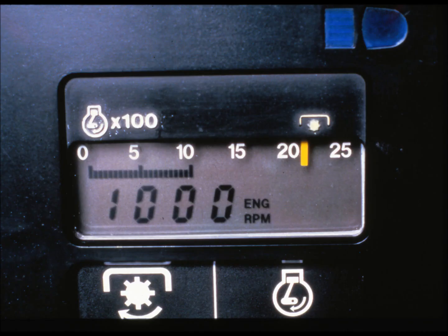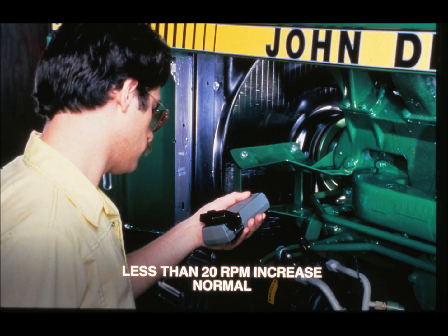With the rock shaft up and all other control valves at neutral, run the engine at 1000 RPM with the pump in stroke. Record engine speed before and after destroking the main hydraulic pump. If the tractor you are diagnosing does not have a digital tachometer, use a photo tachometer. Precise RPM readings are important in this test. If engine speed increases by less than 20 RPM when you destroke the pump, high-pressure leakage to return is acceptable.